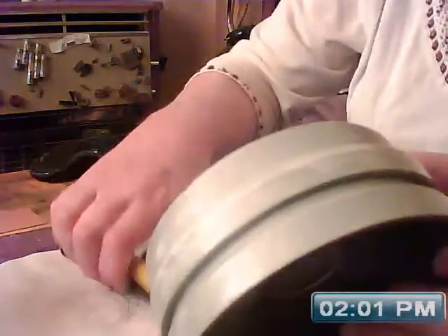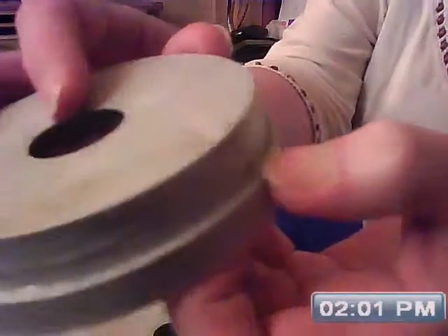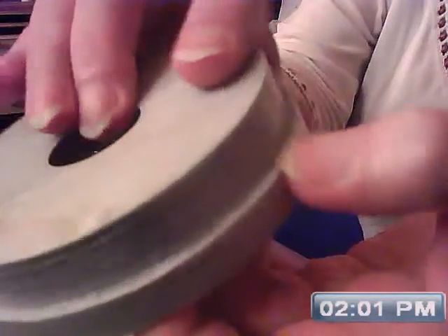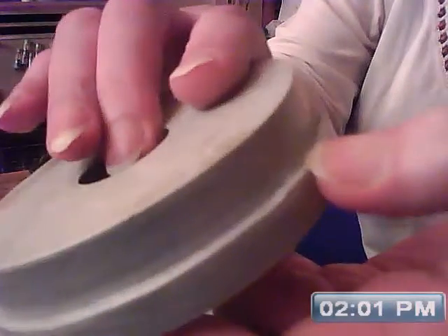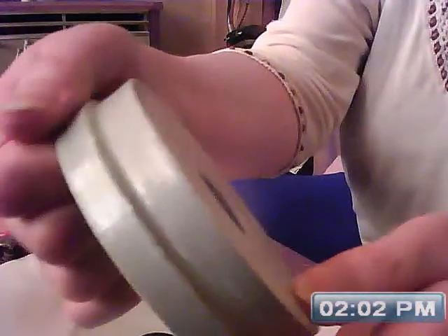Absolutely no sandpapering whatsoever. And the second one I did, if you look, the first one I printed had support material, and look at that edge. It's gross. It's really rough and bumpy. Don't know if you can see that. It's got little holes where the support material was. I 3D printed the new one without support material with a slope on it, and look at that, so much better. Perfect smooth edge, no scarring on it, and because it's a 45-degree angle, there was no need for support material.